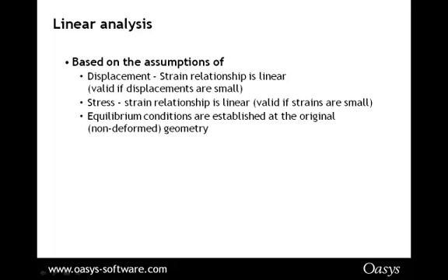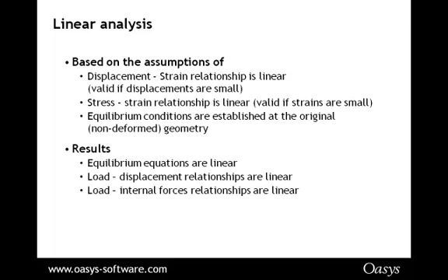This means that it's assumed the geometry doesn't change during analysis. I mean, you do get deflections, but it's assumed they're not significant deflections, and therefore for the equilibrium equations in analysis, it's assumed that nothing actually moves. End results: linear equilibrium, linear load displacement, linear load forces.